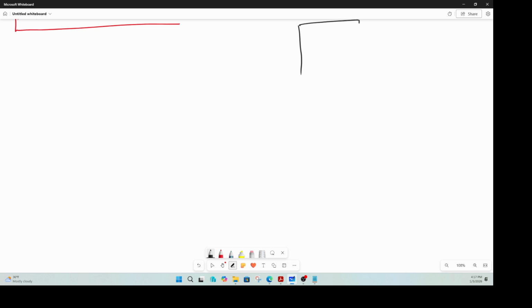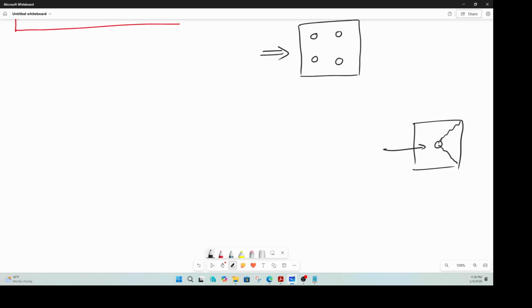So this is our column like that, and we have anchors. We have another anchor here, right? This is looking from the top, and there is a shear. So when you apply shear like this, remember when you have an anchor like that and you apply shear, we talked about this yesterday, or in the previous session. The failure surface looking from the top is going to be this wide.